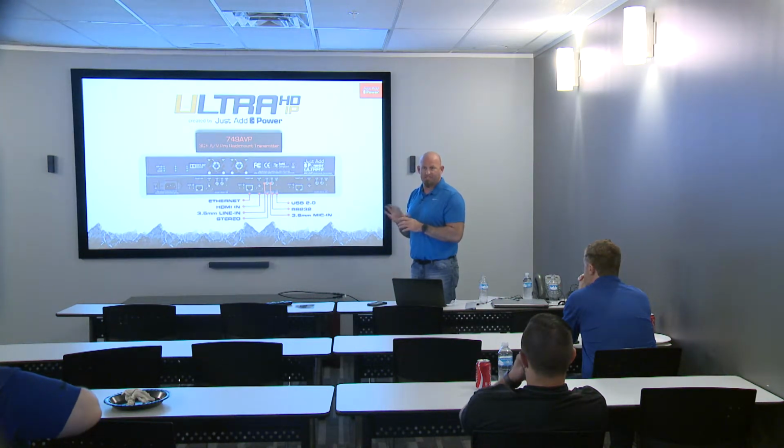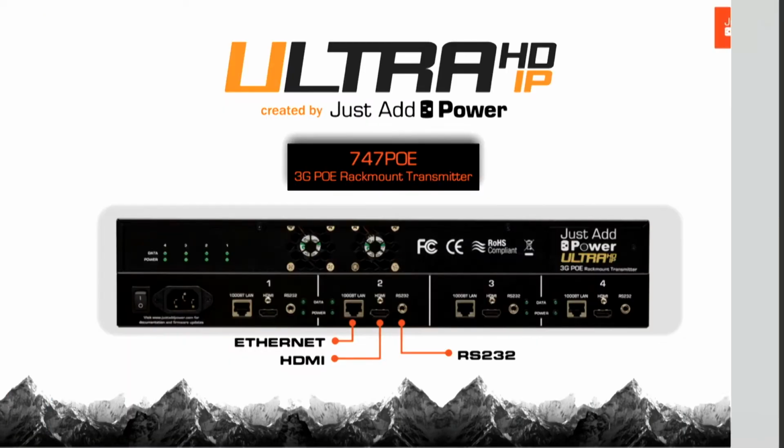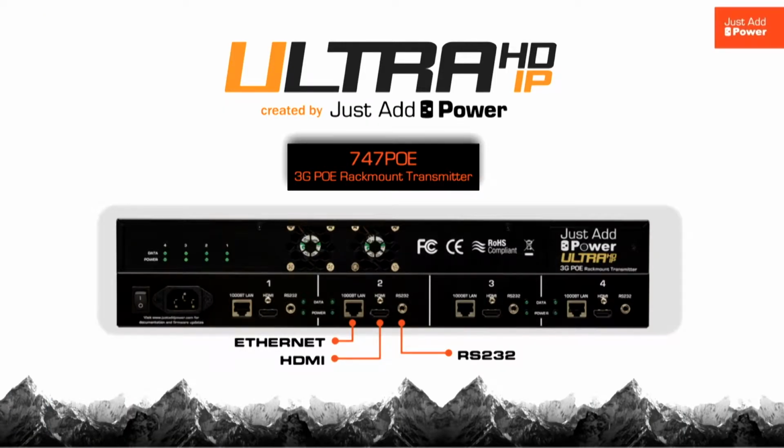You see it some in residential applications, but again, this suffers from the Dolby Pro Logic and Dolby Atmos, DTS:X lossless audio issues. So instead of using this one for residential, you can use the new 747 PoE 3G 4-in-1. This is essentially 4 transmitters in a 1U rack shelf with active cooling. And this is pretty neat too: it is both PoE powered and regular power supply powered, so you have the option of how you want to power it.